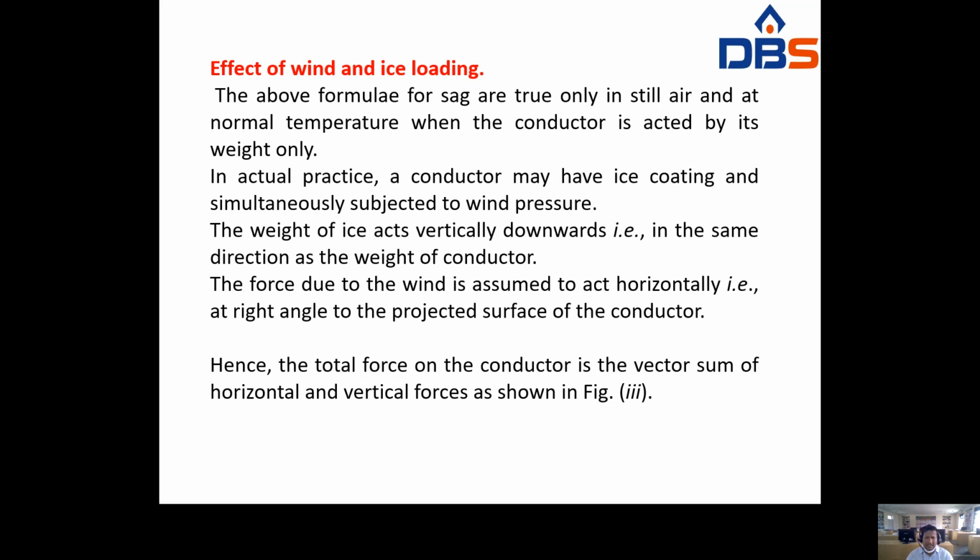The above formula for sag is true only in still air and normal temperature. When the conductor is acted on by weight only, that means in normal temperature, the conductor is mainly acted on by its weight only. In actual practice, the conductor may have an ice coating and be simultaneously subjected to wind. The weight of ice always acts vertically downwards, in the same direction as the weight of the conductor.